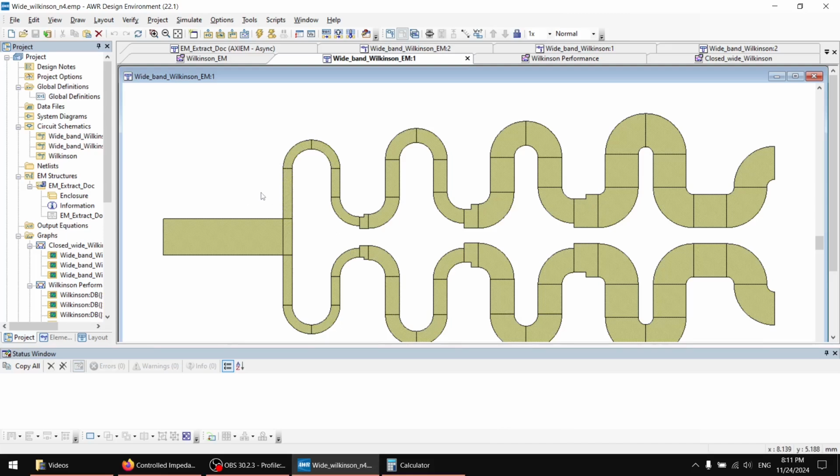However, if you are, for example, designing microwave structures that use this microstrip technology, for example, to create low impedance points, you might find that the widths are just not suitable for your design. For example, in the previous video, I showed you the low pass filter that required a high impedance trace, and this trace became too narrow to implement.